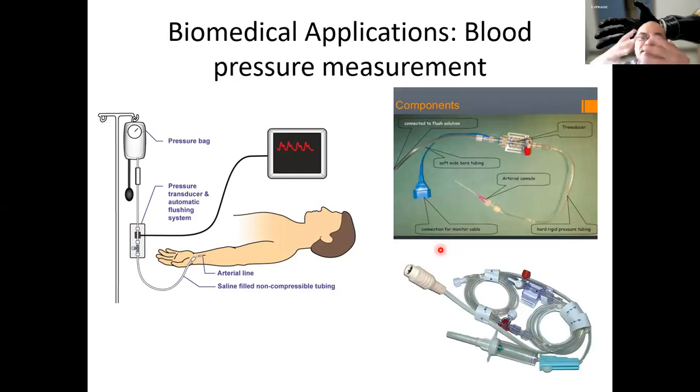When a diaphragm, a membrane, deflects, some regions within its surface are stretched and some regions are compressed. Then you can put the appropriate strain gauges in these different regions of the diaphragm, which will detect the deflection as delta R, resistance change. The resistance change can then be converted into voltage change using a Wheatstone bridge secondary transducer.